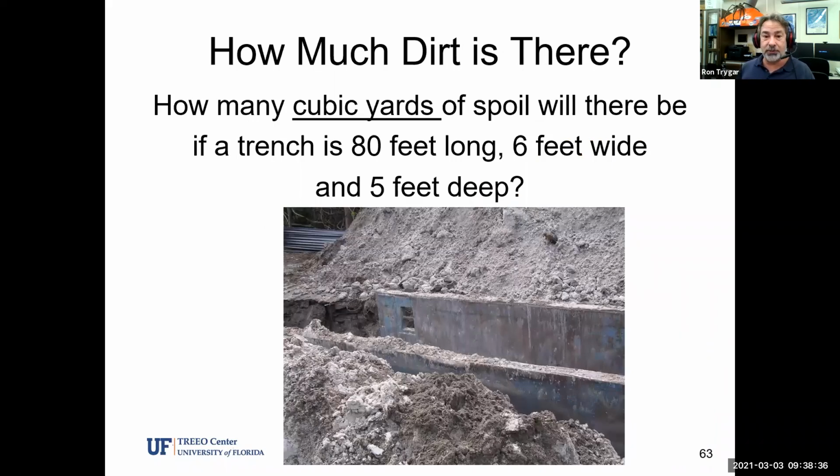All right, so this question says, how much dirt would be removed in cubic yards? We call it spoil, or the leftover material. How much dirt or spoil will be removed from a trench? The trench is 80 feet long, 6 feet wide, and 5 feet deep. So how many cubic yards of soil were excavated from this? What we need to remember is that there's 27 cubic feet in 1 cubic yard.